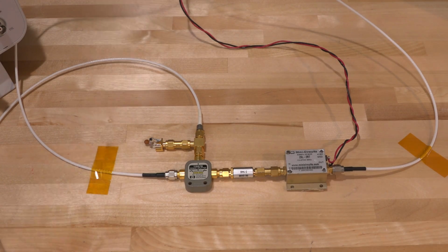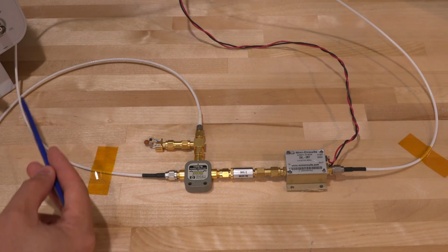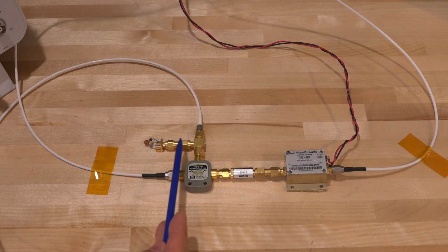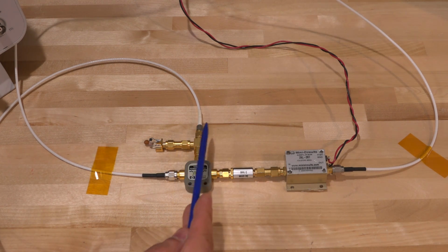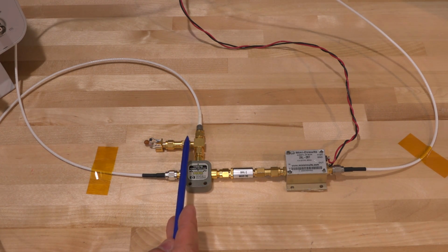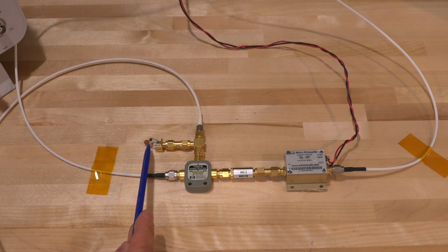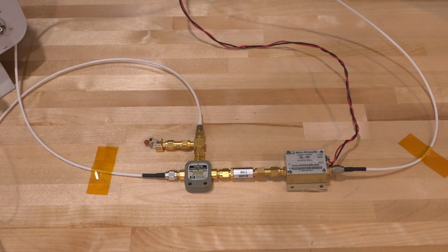So here is our device under test. We have the input coming from the function generator into this T-junction. This T-junction is just a direct short. So at low frequencies and even up to a couple of 100 megahertz, you're basically having a direct short here. At the end of this, I have a capacitor and a diode, a germanium diode. Now the combination of the capacitor and the diode creates a nonlinear impedance.